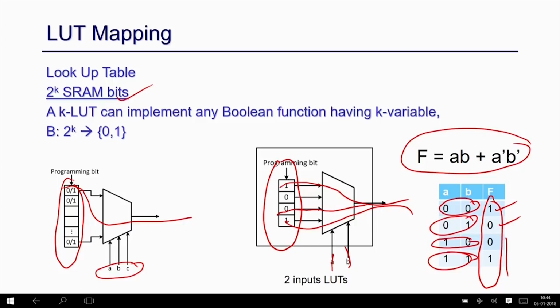So, this is the primary part of technology mapping, because you can understand that in a big logic circuit where we have millions of gates, our objective is to map all the gates into some LUTs, right. This is the overall objective, and as I mentioned earlier also, mapping one gate into one LUT is not acceptable, because finally you are not going to implement just a single gate in this LUT.